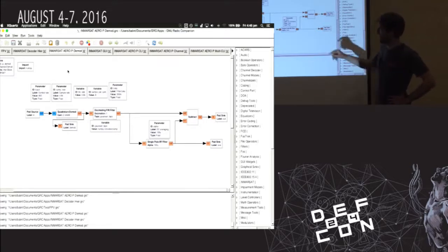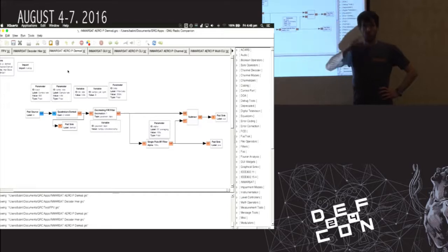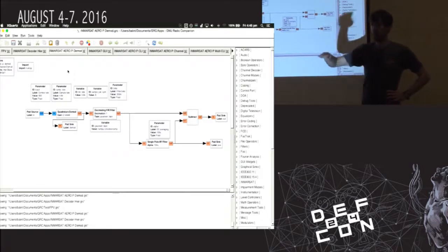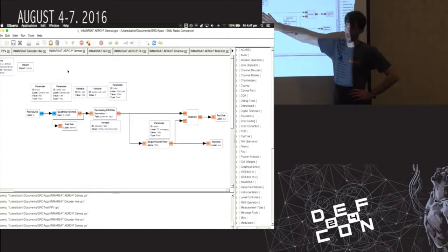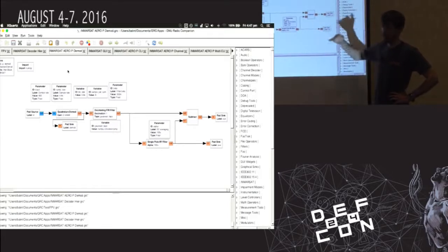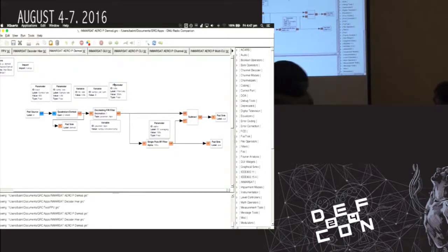That means that we have a lot of transitions, and so if you average that over a very long period of time, that should average to 0. And so what we can do is that long-running average and then subtract that from our original signal, and then we will get something that's actually nicely sitting around the 0 point, and you'll see why that's important in a second. So this is the demod part of it, very simple.